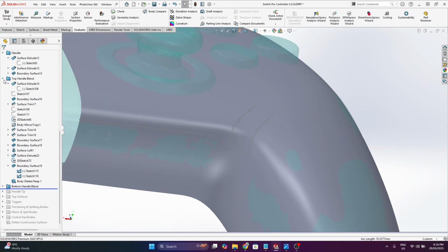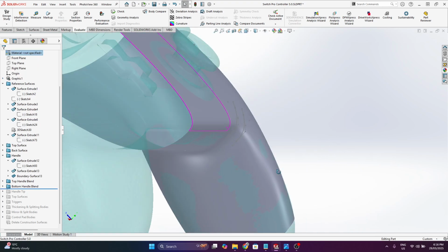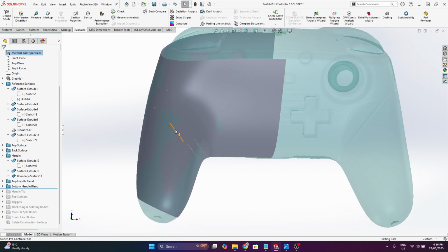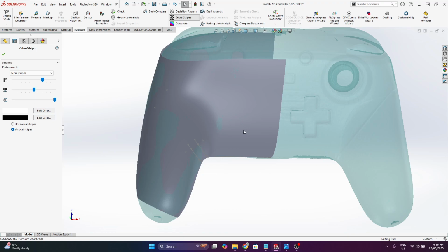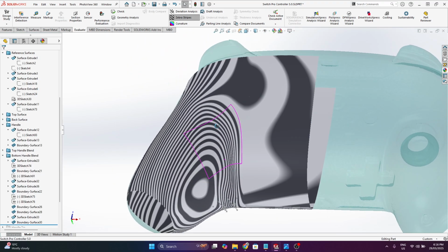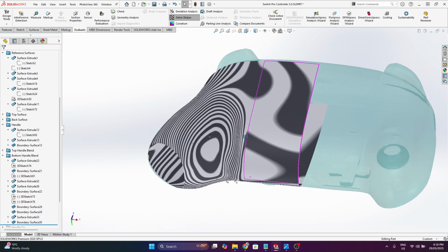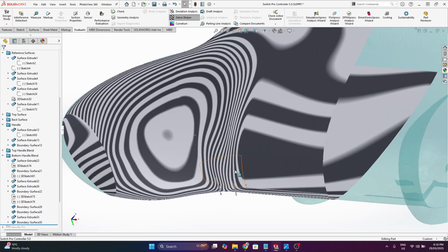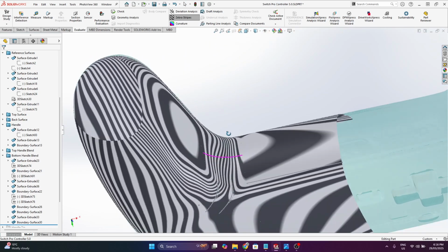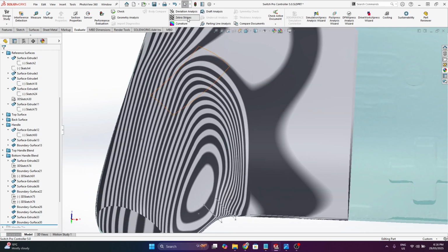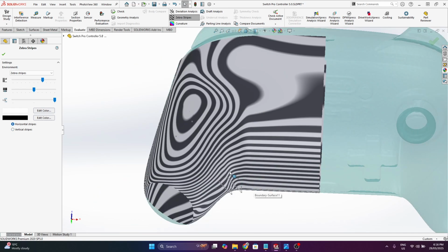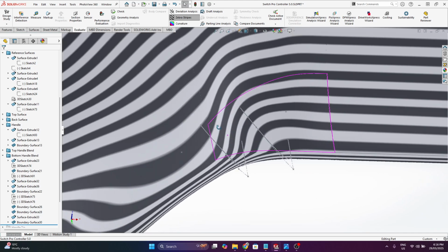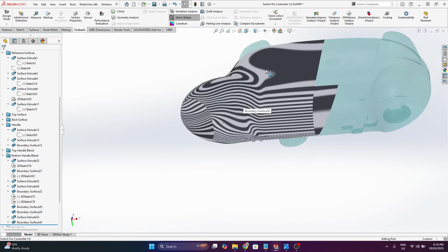So moving on to the blend on the back or bottom side. This was fairly difficult for me to make reasonable. Definitely didn't get it perfect, but quite happy with the transition here, with the zebra stripes giving a nice flow and indicating where the tightest curve runs. When using the zebra stripes, it's also important to switch between vertical and horizontal. And again, not perfect, some wobbles, but overall not too bad.